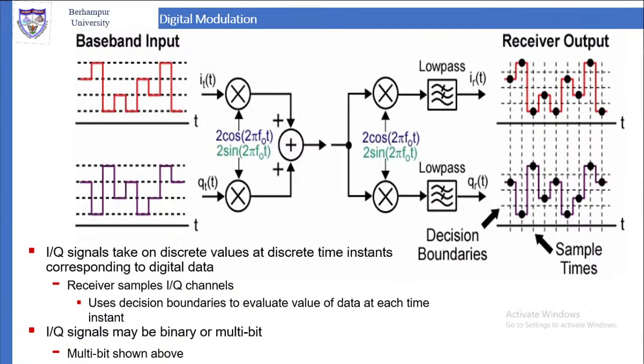If you sample at that speed, then from the sample points we can recover the signal. So 2f is the minimum frequency of sampling. It should be more than or equal to 2f to get back the original signal. So let us take a signal and take its samples.